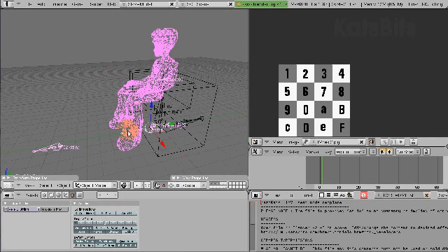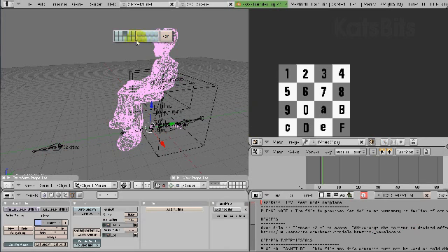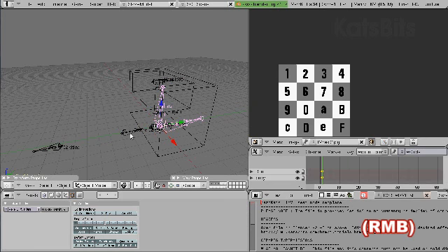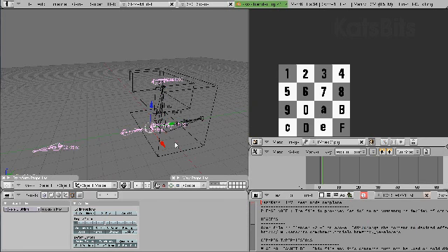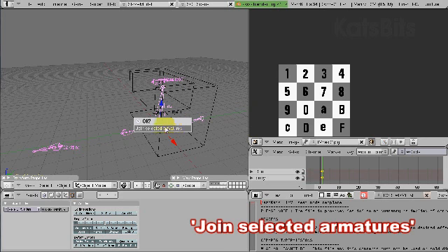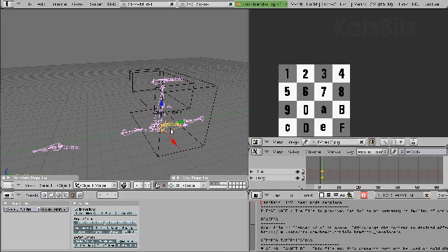Before we do that, we need to move the helper mesh because we no longer need that. So just move that to another layer. Right mouse select, M key, click one of the layers and OK. First things first, we need to prepare the armatures. Select the seating armature, then the furniture armature, then using Ctrl J, join the two together. What we need to do next is change the relationship between the bones so that they're set up correctly relative to what IMVU is expecting to see in order for this to work.